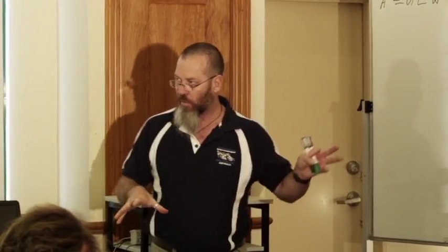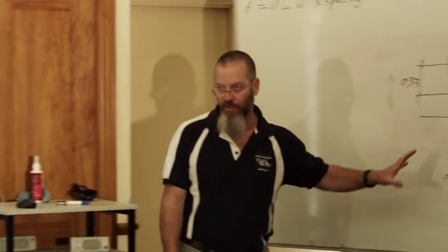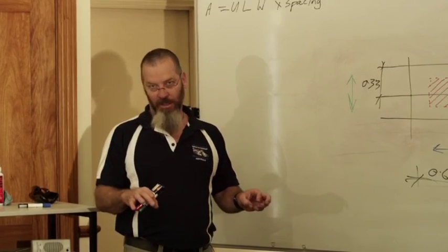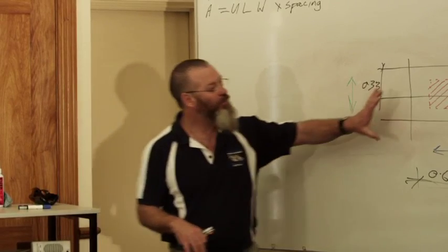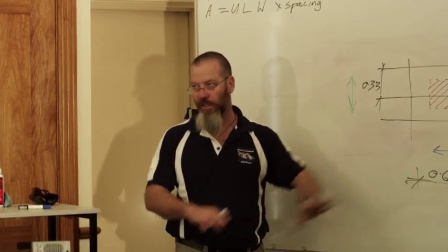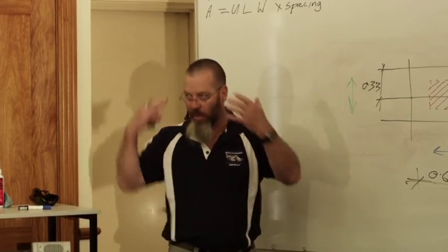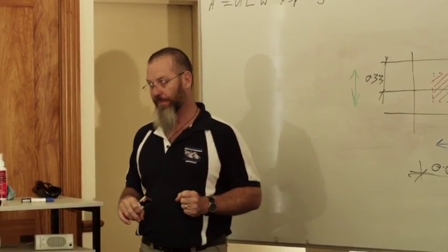What part or the area that's contributing to suction or uplift on that connection? That's it there. You can actually do it mathematically, but I'd encourage you to do that drawing first or do that sketch first. You'll see there, my drawing skills are not great, crappy in other words, but I've just done a single line sketch. I haven't used AutoCAD or even a ruler or set squares, just do it that way, and I can get into my builder's head now exactly what I'm talking about, the tributary area.